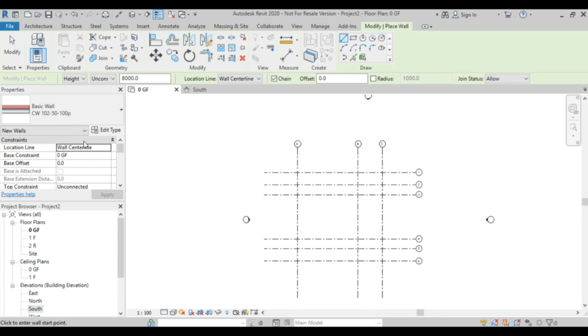But you need to be aware that if you create a custom wall family in one of your projects, you have to recreate it in the others, because you cannot save it to the hard disk. You can either recreate it in the new project, or you can simply copy and paste it into the new project. That's one thing that you have to understand.